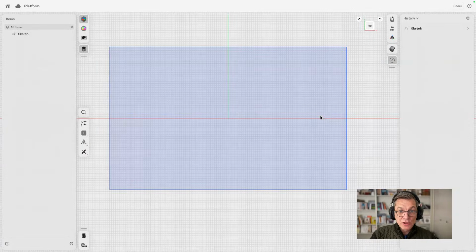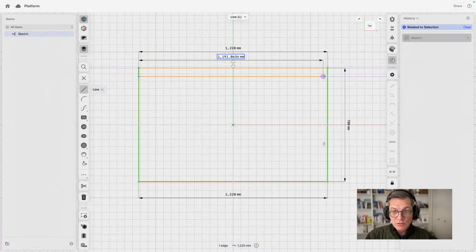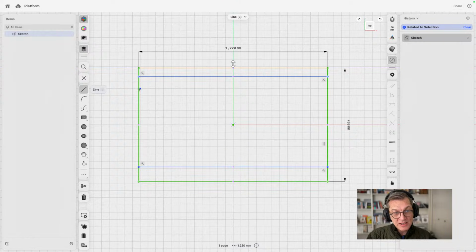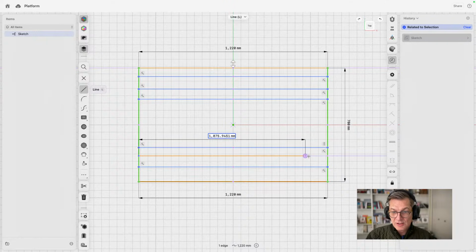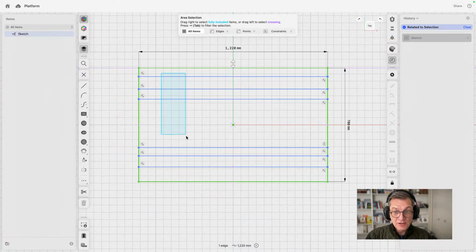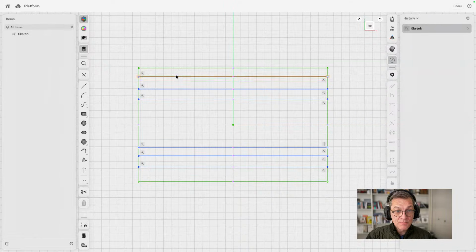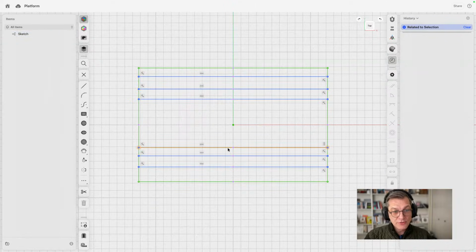And if I now go to the sketch, I have to block out, for example, the amount of pipes I need. I know I need one pipe there, one pipe there. I sketch them in very loosely, as you can see. There and there and there. Ideally, all these lines should be perpendicular or horizontal, so they have a coincidence. So I can select these lines, make them vertical, horizontal, so they can rotate.